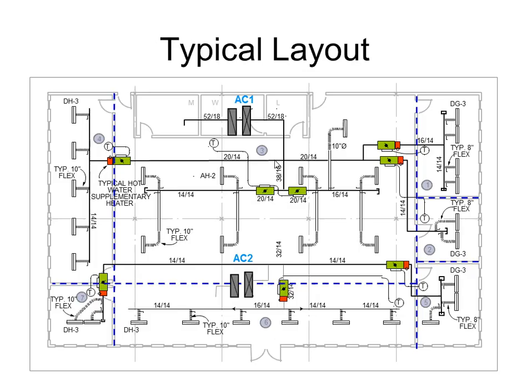Here's another conceptual layout of a VVT system. We have 2 air sources. We have AC1 up here and then AC2. AC2 serving the south side of the building, and then AC1 has the rest. As you can see, AC1, we have 5 zones off of here. And you can see these little red boxes are for supplementary heat.